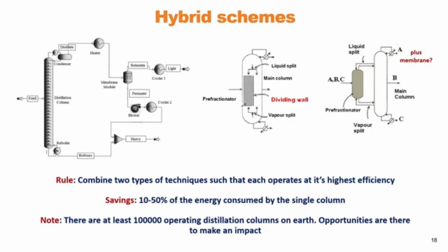By the way, in this presentation, the case study of the HDA process using the hybrid distillation scheme has not been considered. With this slide, we highlight the hybrid scheme for further reduction of the energy demands. The method first identifies the most energy-intensive separation process, and then applies the rules. If a match of the design target is found, then significant energy savings are possible through the hybrid scheme. Our application with hydrocarbon processing by distillation shows that between 20 to 40% energy can be saved.